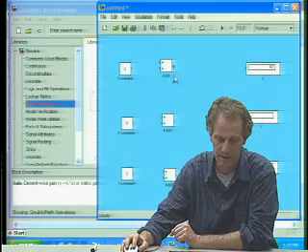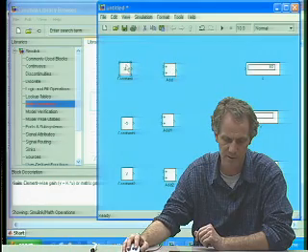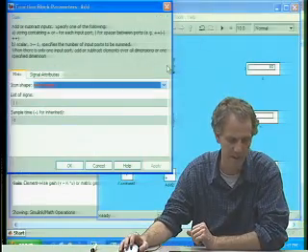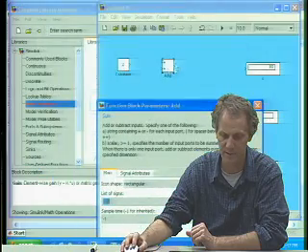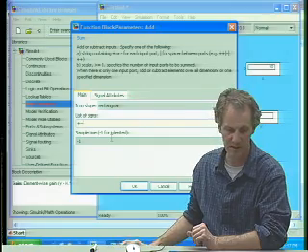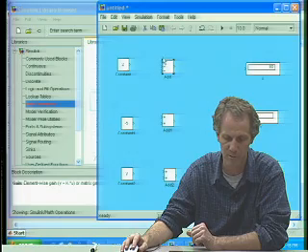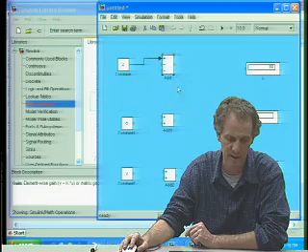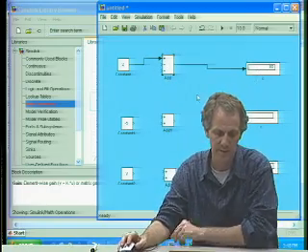And then for my additions, let's just do one equation to start with. This was the equation 2 minus y minus z. That's a plus. I double-clicked on the summation block, and it gives me a chance to change the signs and add new signs. I want it to be plus, minus, minus. So now there's actually 3 input ports instead of just 2 input ports. And I want my 2 to go into the first one, so I'll control-click. Now I've got a 2 in there. And after I get done with that calculation, that's going to be x.